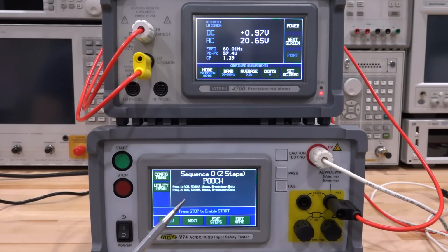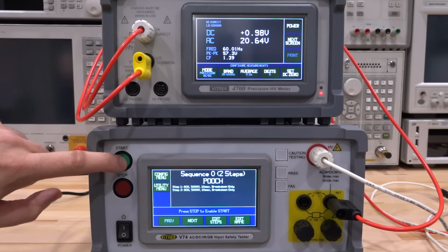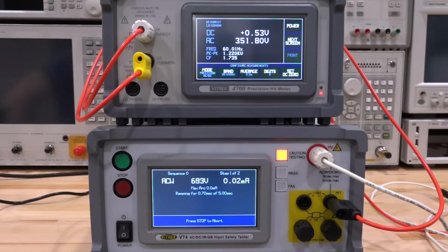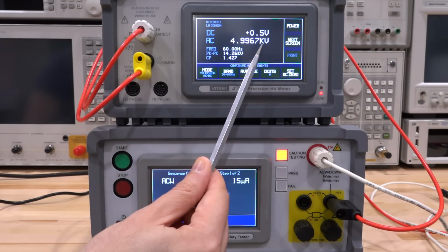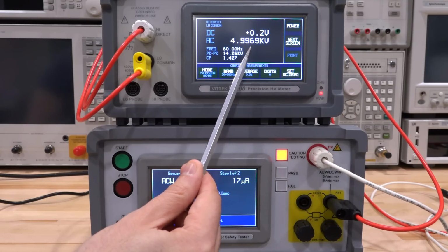It's interesting that when everything is turned off, there's a 20 volt AC coming out. Must be just picking it up from internal transformers and everything else. Here we go. We start this test. If I can do that. There we go. So the test is running. You can see it's ramping up, and this is also ramping up, and it's going to reach 5,000, and it's holding it now for 10 seconds. Look at that. 5,000. It's not very stable, but it's good enough for the purpose.